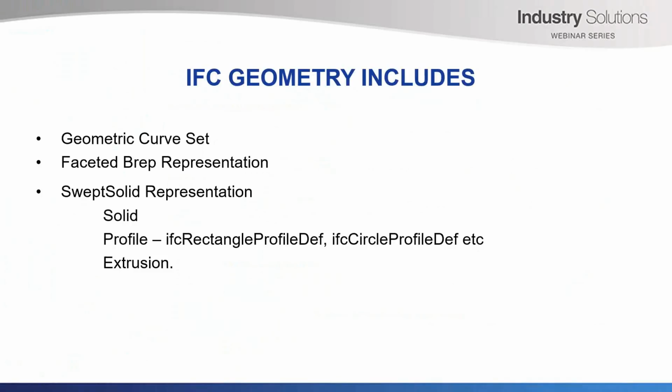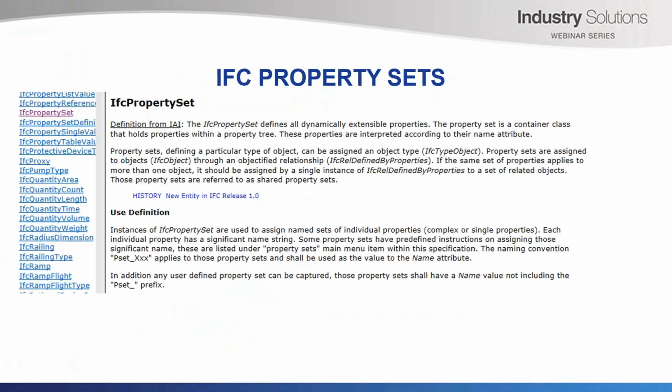Now, what on earth is an IFC property set? And this is very important. It's just the name to a set of attributes. So you can have attributes just like you can have them inside 12D model. They can be hierarchical, but when you define a set of them and you say what they all are, they have to have a name. So we have string attributes at the top level which don't have a name. What you really need is your attributes have to be in, say, groups, and you would use that group as a name for the property sets. So basically, though, it can have a hierarchy of them, just like we can have.